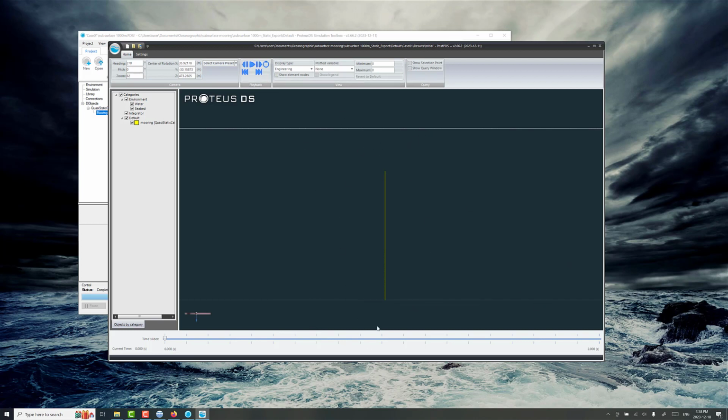So this is the initial position of the mooring. The first calculation step it'll do is calculate the stretch of the mooring in no current, and because it's wire, it's very stiff, there's barely any change in the elasticity. And then we see the deflection of the mooring in that current profile that we've got. So that looks about right, just very generally. We had a reasonable amount of tension, but not a lot. And you can see there's some reasonable horizontal deflection.